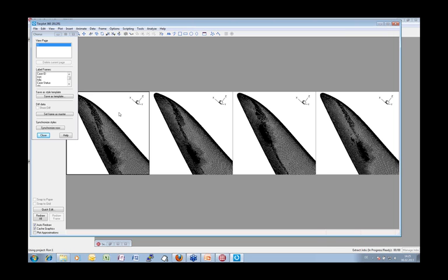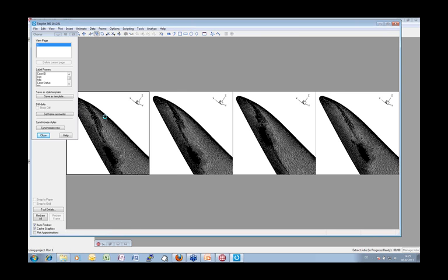What I can see here is that the adaptation parameters have been set correctly, and the trace of the vortex should be visible on the surface, and it does, yes. In the vortex, higher gradients occur, and therefore the adaptation inserts mesh points here. As I see, the adaptation has worked as I expected it. Oh, that's great. Arno, what's the next step? What can I do next?